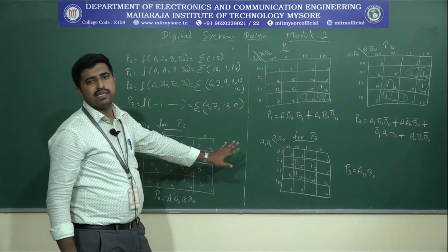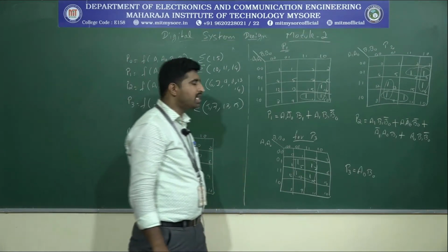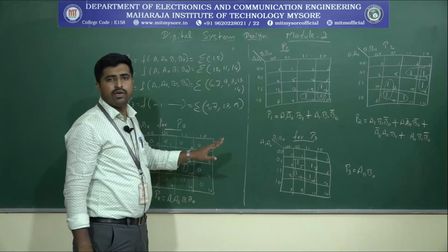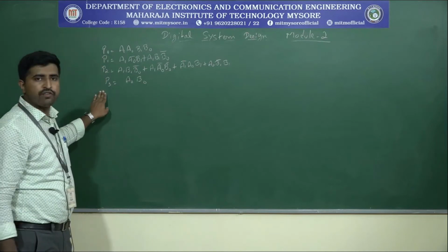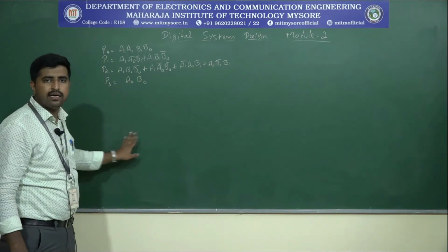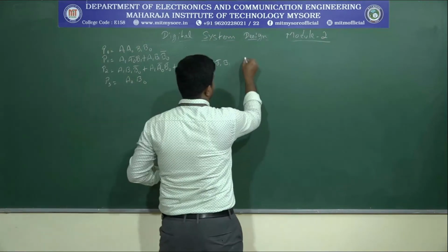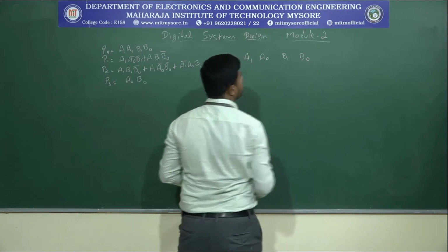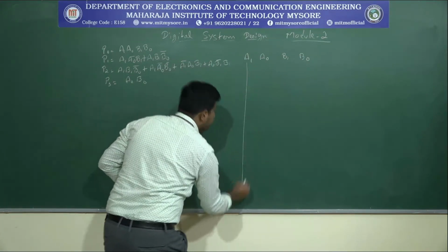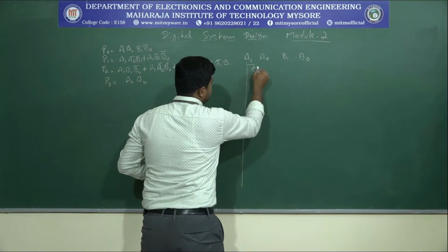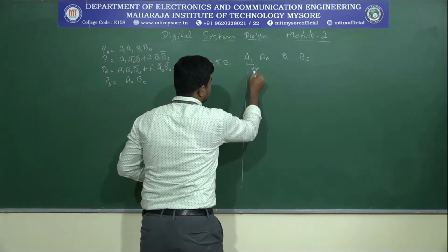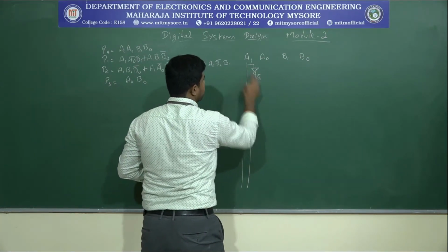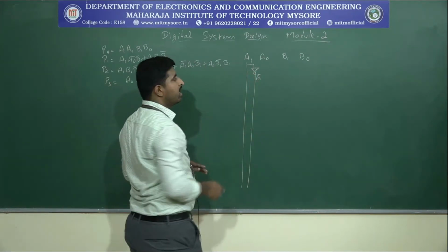Now we need to realize these equations by using the logic gates. So let's write the logic diagram for all these 4 equations. Let's design the logic diagram. Okay, so we have the inputs A1 A naught, B1 B naught, right, and we may have even the complement form also, right. So here only I will write that one. This corresponds to A1 bar, this corresponds to A1, and this corresponds to A1 bar.